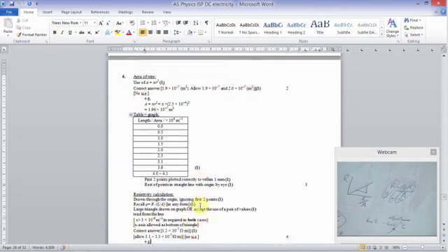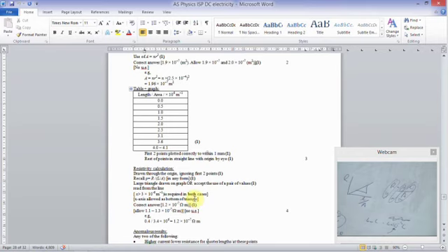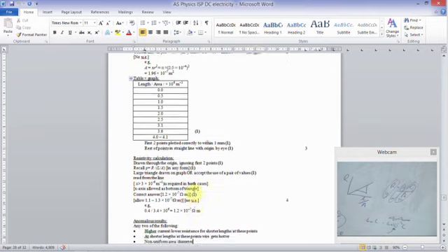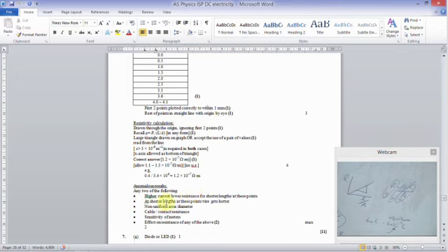Okay. So again, resistivity calculation is a straight line drawn from the origin, large triangle, so it's just find the gradient, remember. So the ideas are higher current or lower resistance for shorter length. Okay, so remember, when a short length you get a high current, that will affect the resistance. We've spoken about that in class. Non-uniform area or diameter, so we've spoken about that as well. And contact resistance, we've also spoken about. Sensitivity of meters, that's what I was talking about in terms of the fluctuations.